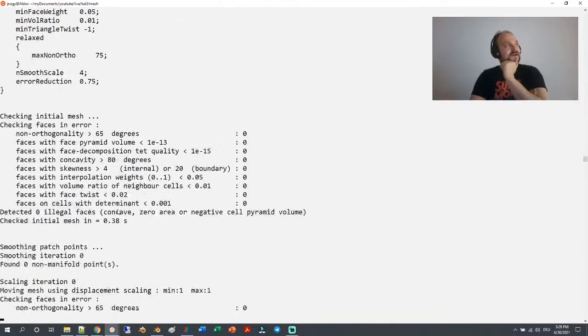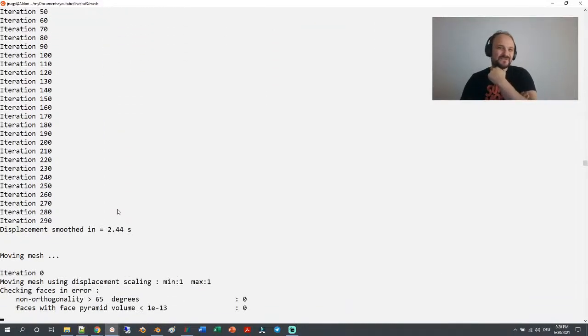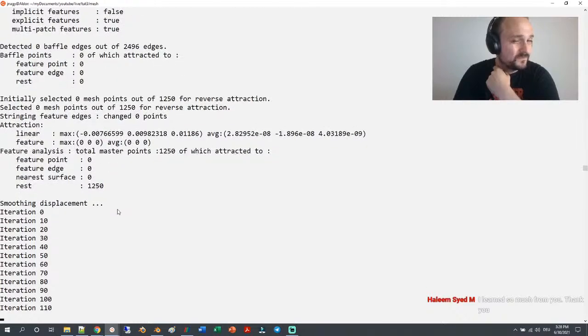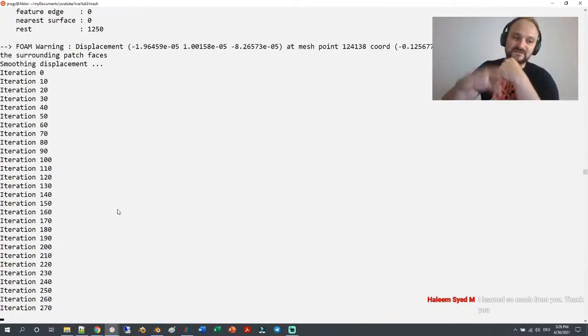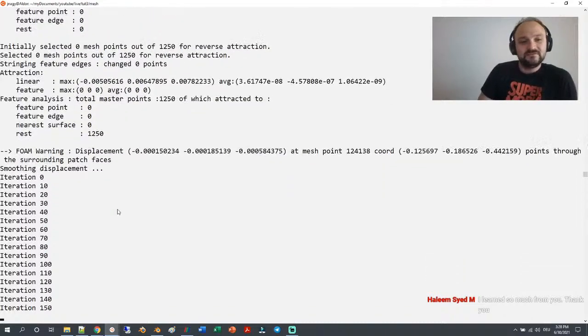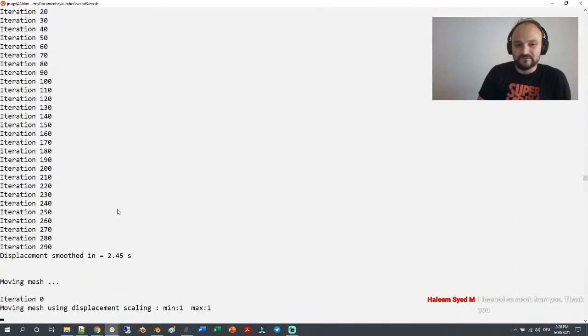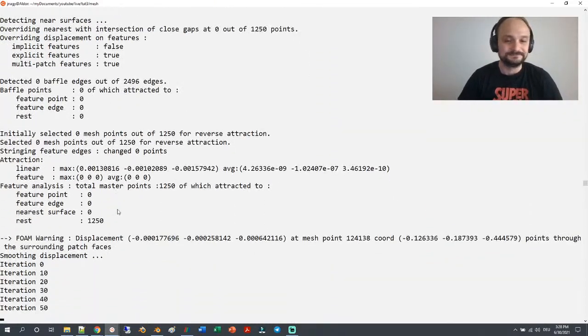So yeah, I thought about whether it would be a good idea to do this steady state, but I don't think so. Especially for turbulent phenomena, I think we should concentrate on transient flows and then get a mean value of the CD value and compare that. So yeah, I will start with pimpleFoam and go from there.